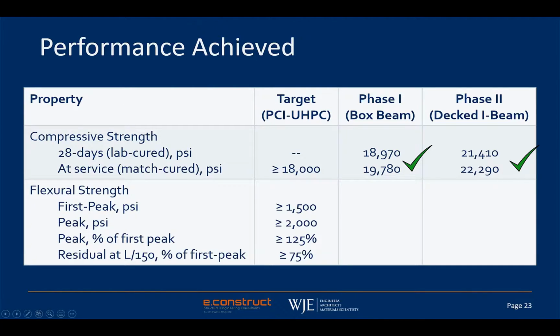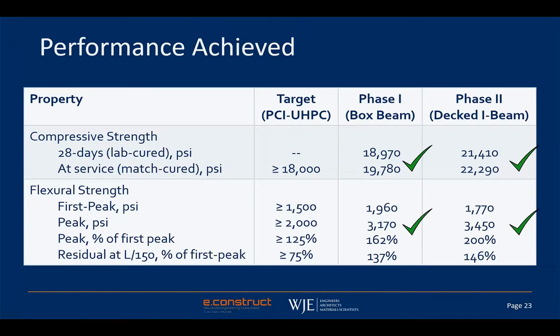The flexural strength and ductility also well exceeded the targets, with the ultimate flexural strength of over 3,000 PSI relative to our target of about 2,000. And certainly our peak as a percentage of the first peak also far exceeded our target of 125%.